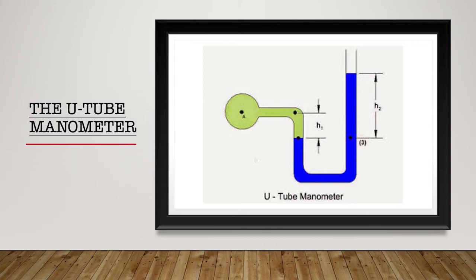Manometers have connecting U-shaped tubes containing different fluids. When one limb of the manometer is open to the atmosphere, it records the pressure of the source connected to the other limb. When both limbs are connected to pressure sources, the manometer records the difference between the two pressure sources. Simple manometer and differential manometer are what these manometers are called.